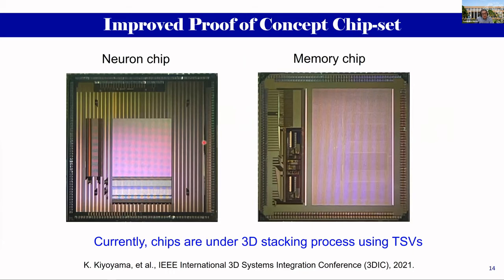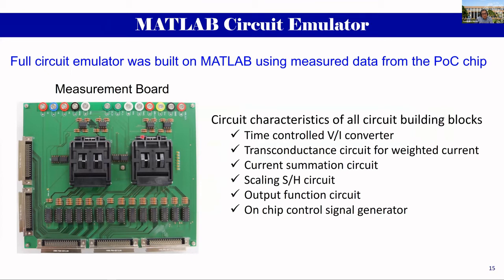However, we measured the chips using this kind of board. And using the measurement results from the chip, we built a full circuit emulator on MATLAB using those data. And this MATLAB emulator includes almost all of the circuit characteristics of the actual chip. So we now evaluate the system and our algorithm.